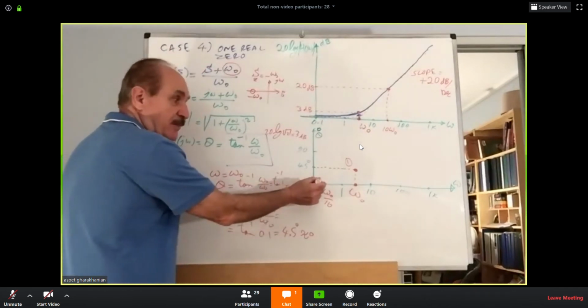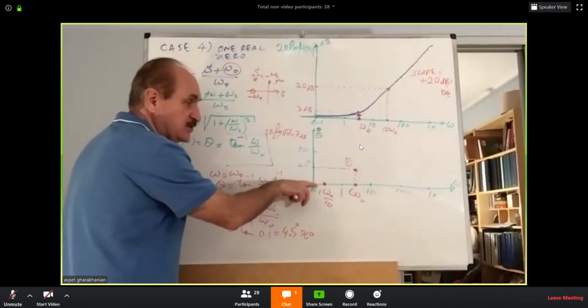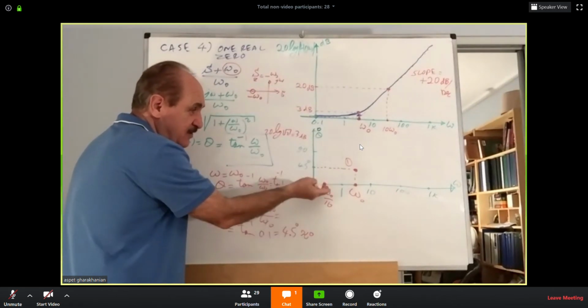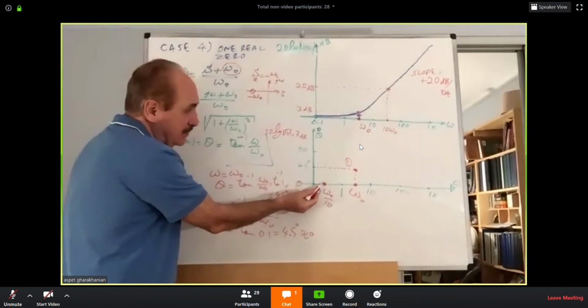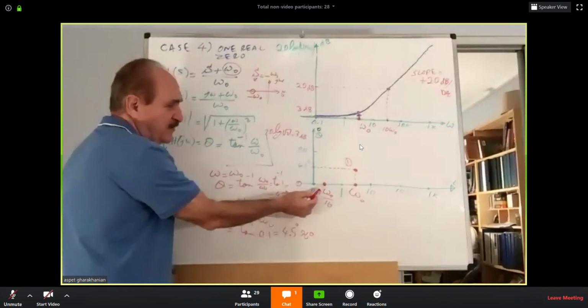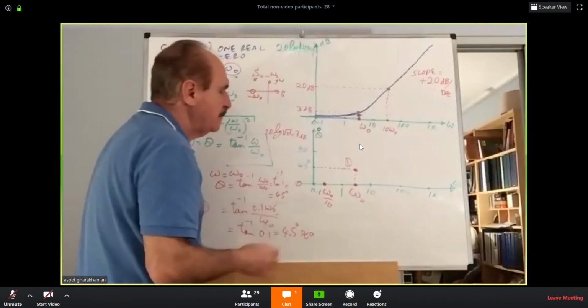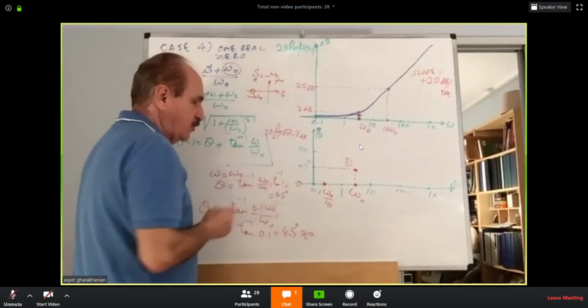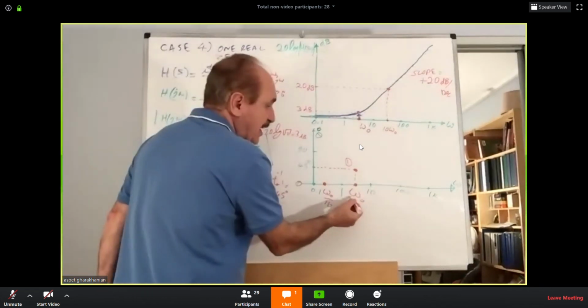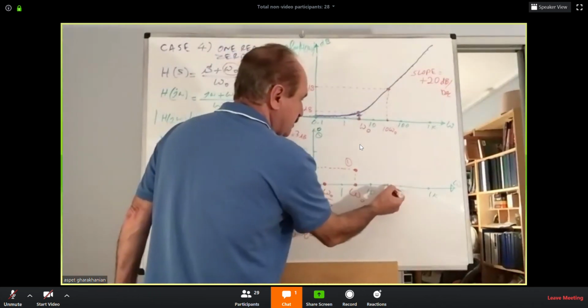So this is just an approximation. The curve does not pass through that point. It's 4.5 degrees higher, which is like 10% relative to that level. So kind of 10% higher, small. But we will mark this one. Next thing is go find 10 times that frequency. It's here.